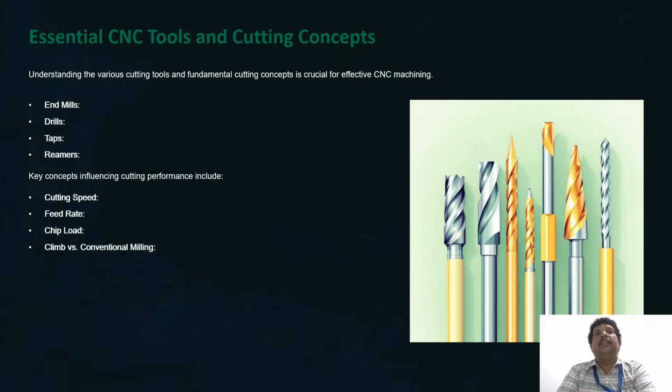And reamers. Reamers are used for reaming purposes, where we have to align two plates together. Sometimes we cannot use a screw. What we'll be using is a dowel, with the exact fit. The main concern will be the fit. So we will have the H7 G6 fit. When we need the H7 fit and everything, we use the reamers.